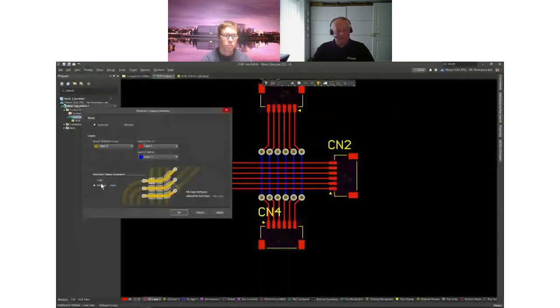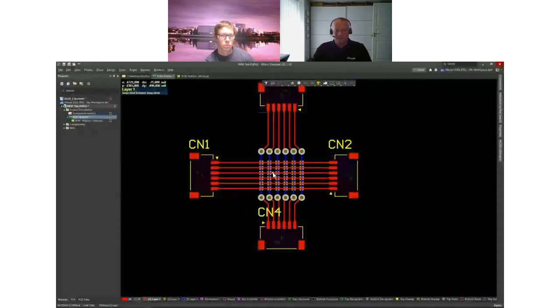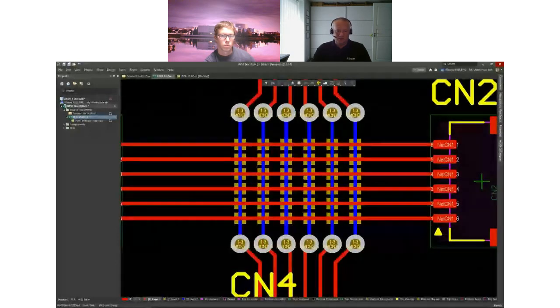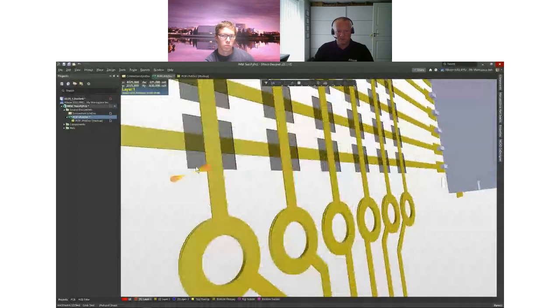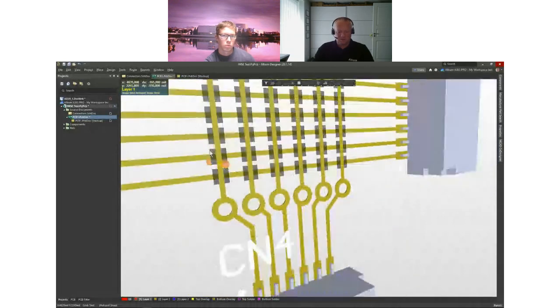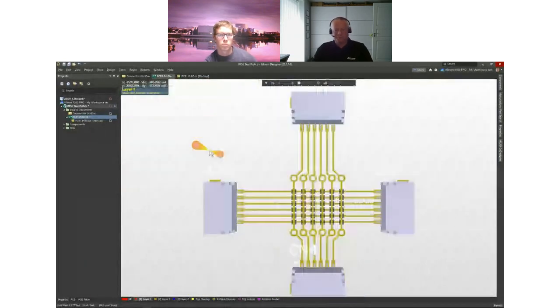For the dielectrical shape here, I can set this one to auto or manually define it myself here. And I can also ask the tool to fill the gaps here. Let's first of all not fill the gaps here, and let's apply this one. So now you can see that the system generated these isolation paths here in layer 3, the isolation layer. If we switch to 3D mode, you can see that it's being represented like this, so there's no short anymore. So this is almost done.